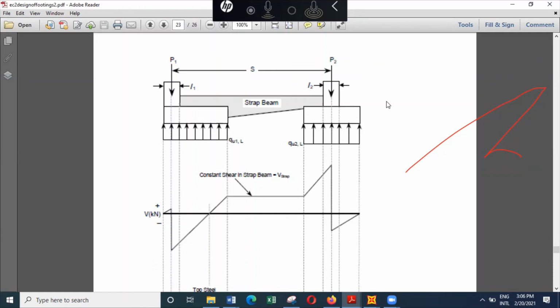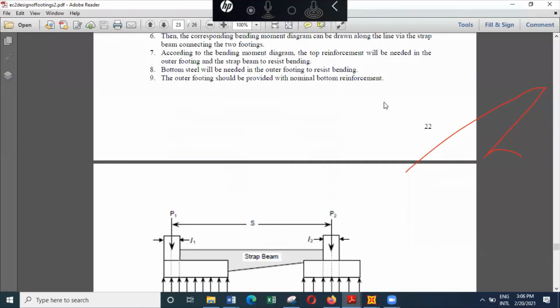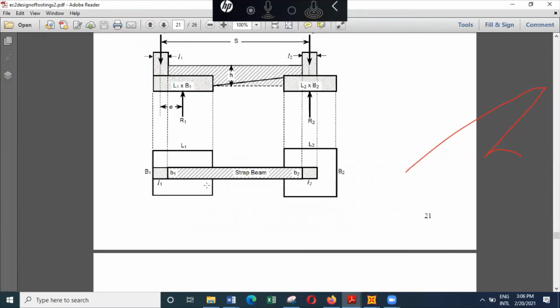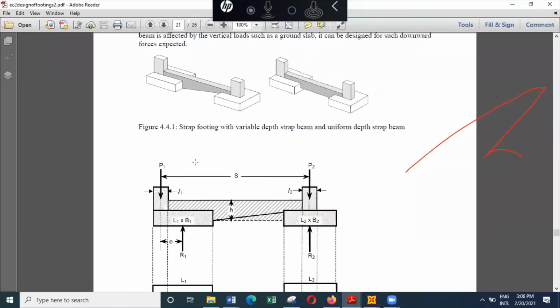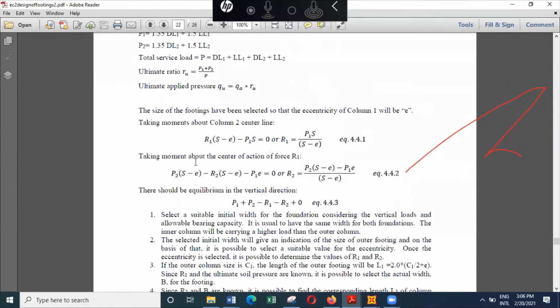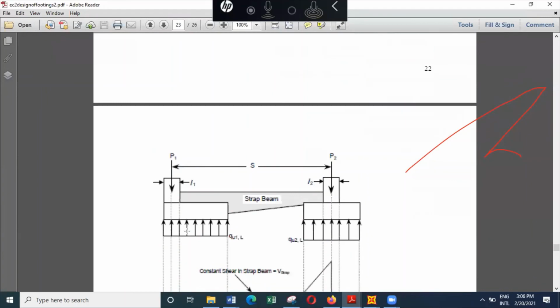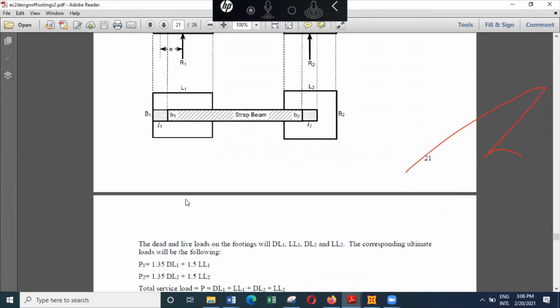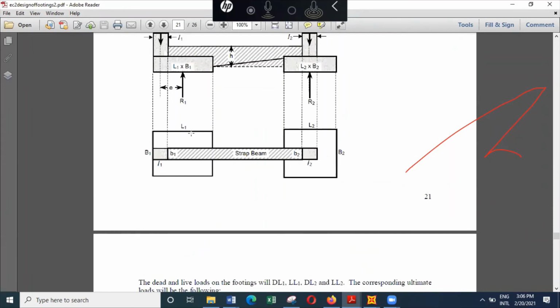Could you explain again the selection of nominal reinforcement at the top and main reinforcement in the base? Yes. Now, if you look at this particular base and at the loading system, you can see it is loaded from below. So you get 206 acting here, which means this can bend upwards.